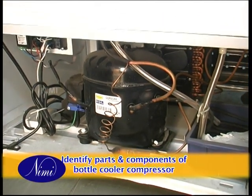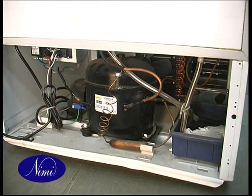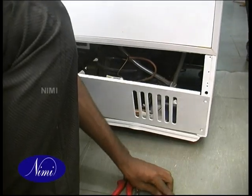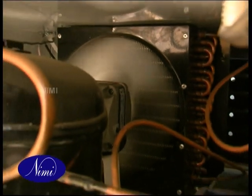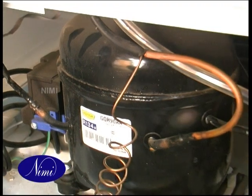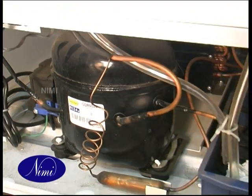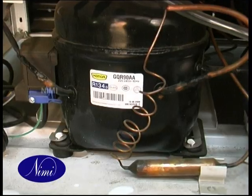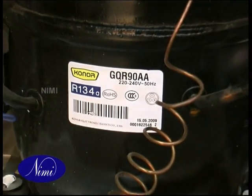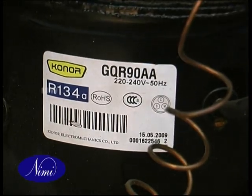Identify parts and components in a bottle cooler. Compressor. Locate the compressor which is installed near fan motor. Identify bottle cooler employing hermetically sealed compressor. Check compressor HP, amps, volts given in compressor name plate.